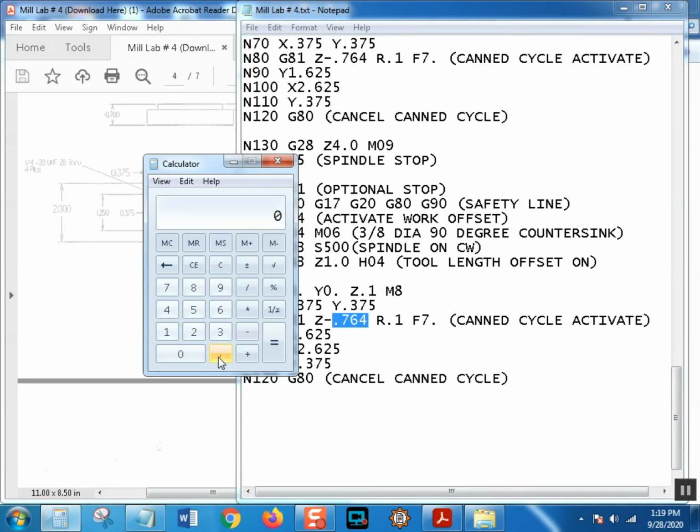So here's how we'll do that. The hole's 250. That's what size it will be, because we want to make a countersink for this. So I got 250, and what am I going to do with that? I want to know how deep I'm going. Had a senior moment there. So 250 divided by 2. Always take whatever the diameter of the countersink you want it to be, divided by 2, and that's how deep you go. Divided by 2, 125 thousandths.